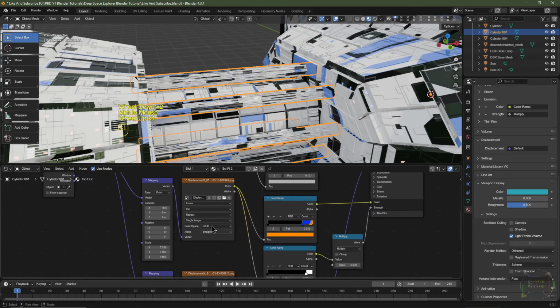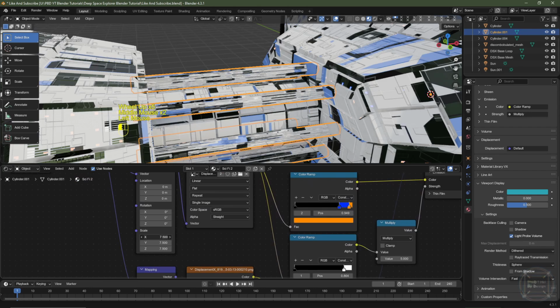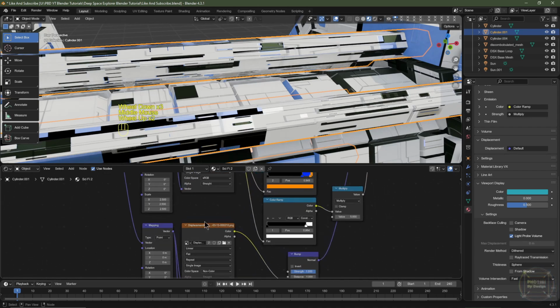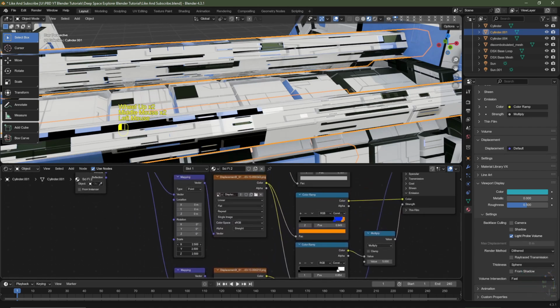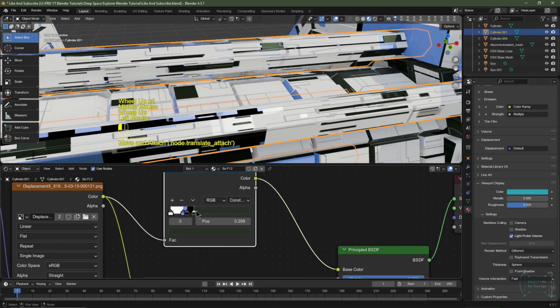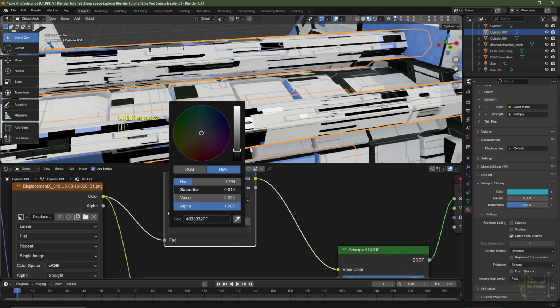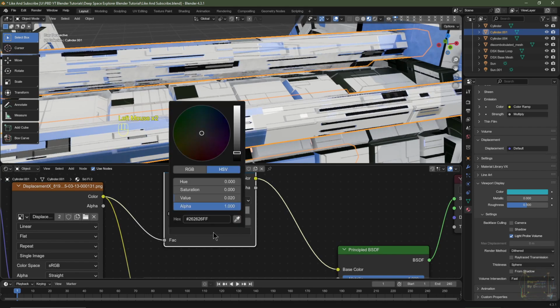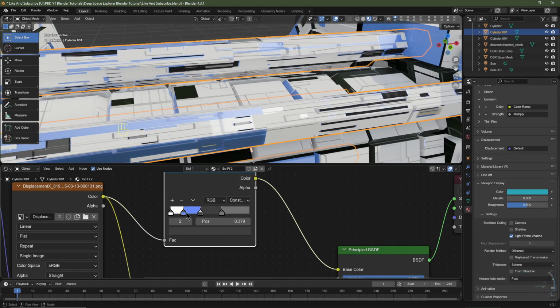I'm going to scroll to the second image texture, and for the scaling I'm going to type in 2.5, and for the bottom textures on the mapping I'm going to choose 0.5. Maybe we'll decrease the middle texture to, let's say, 1. We're just going to change the colours now. So instead of having a green, I'm going to take the saturation all the way down, bring it up to like a grey colour.